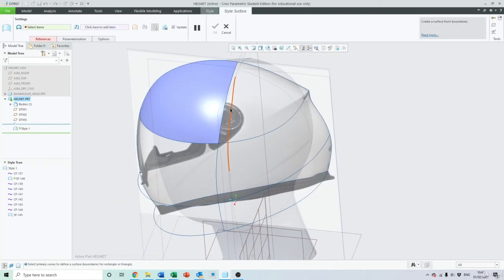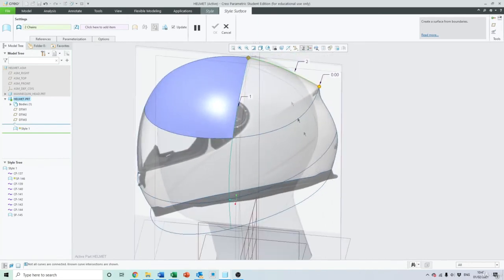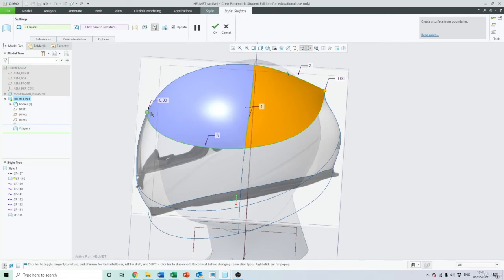And as you sort of understand how we're going to be doing this, we're going to whiz through these. So let's choose this curve first, right click, trim at. Holding down the control key, I'll choose this curve here, right click, trim at this curve there. Yes, we want that section. Control key for the next boundary. And again, the surface is created, but we want to right click, trim at here.